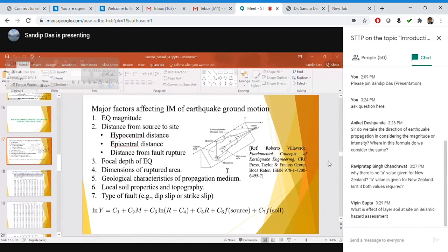So you have to find a very sophisticated attenuation model where the geology of wave propagation is also accounted for. The next challenge is that even if that is accounted for in the model, you have to give this data for your region, and assessing all that sophisticated information for your region is also difficult. That is the reason these studies are more favorable for a region which is seismically very active, because getting data and having a region-specific attenuation model or a and b values are easier.